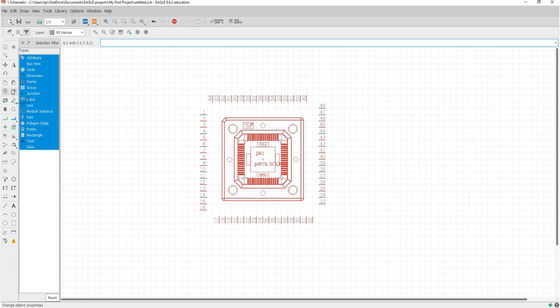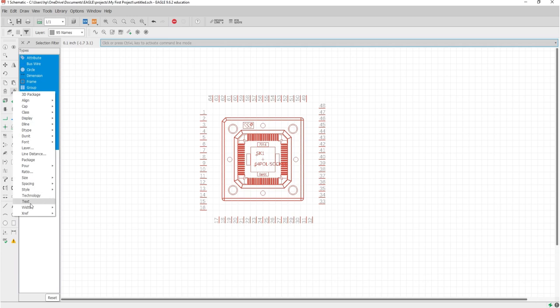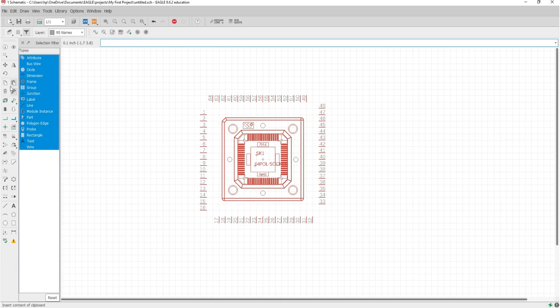This is the Change tool. It is used to change the properties of an object, for example, the width of a wire or the size of a text. If the Escape key is pressed after changing the property, the previously used value menu will appear again. In this way, a new value can be conveniently chosen. Then, this symbol right here is used to add a design block.